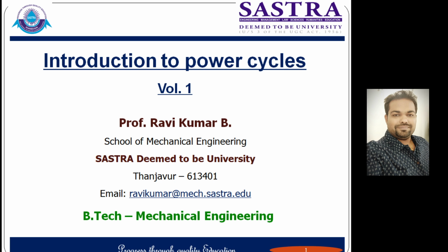You have already been given a general definition of a heat engine. A heat engine is a device which operates in a cyclic way, and its sole purpose is to provide mechanical work for a given input. The input you provide to the heat engine is a given quantity of heat. How much portion of the given heat is converted into mechanical work is called the effectiveness or efficiency of the heat engine. As per the second law, complete conversion of heat into work is impossible, so some portion has to be rejected to the atmosphere in order to produce mechanical work in a cycle.